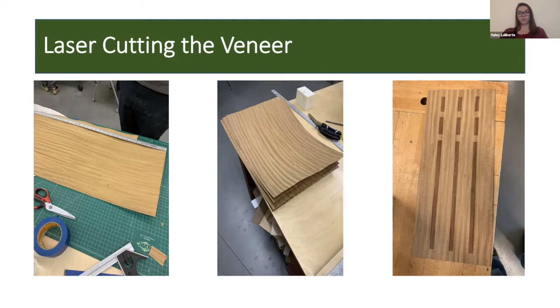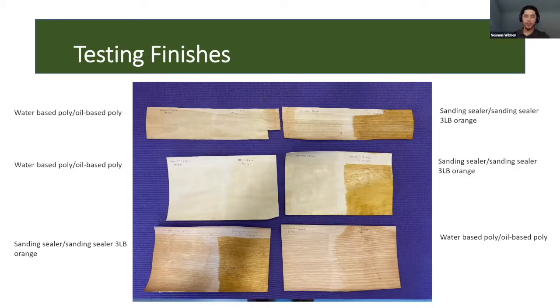without laser engraving it. This is an example of some research we did with different finishes on some scrap pieces of veneer we had. This test in particular was geared to provide us insights on the effects of finishes on different veneer. From this, we decided to go with an oil-based poly finish as it displayed the least amount of warp on the material.